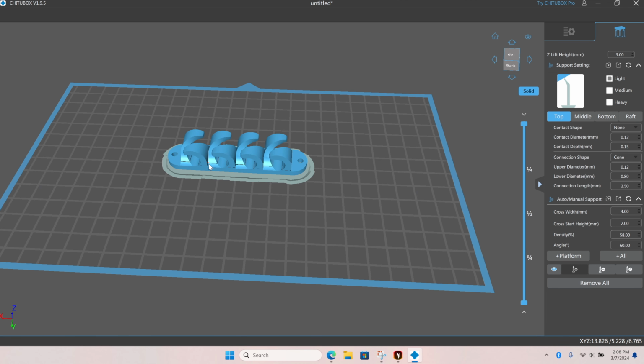You can get high quality prints, and with light supports, you get minimal surface finish irregularities where those supports contact the print. If you're printing something larger or something that doesn't need to have pristine surface finish, then you can either add medium or heavy supports. When I'm in the shop, almost always with larger items, I'm going to go ahead and add auto supports that are heavy. I'll go ahead and show you that now.